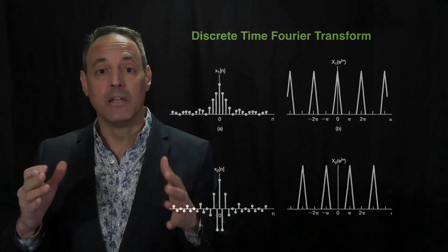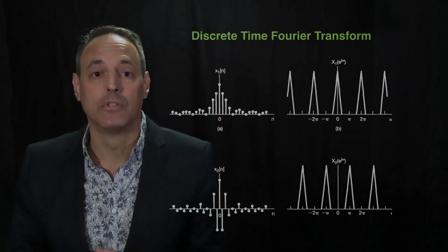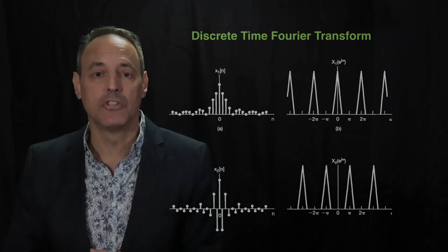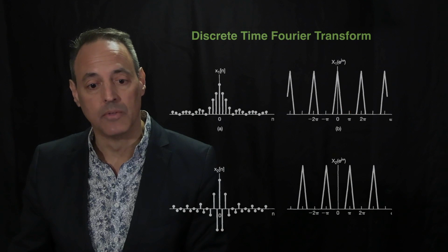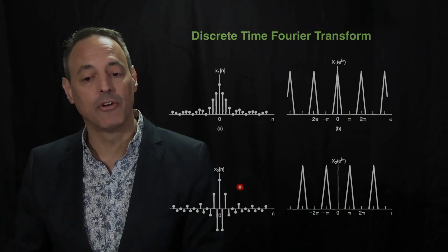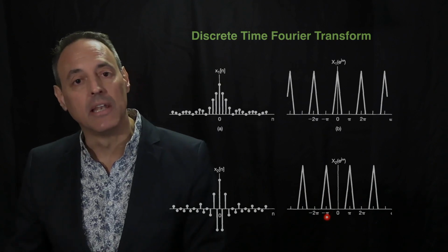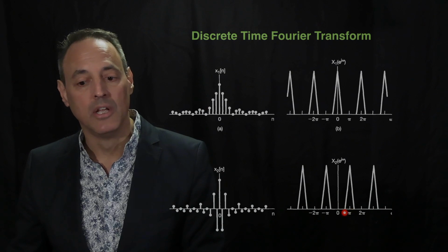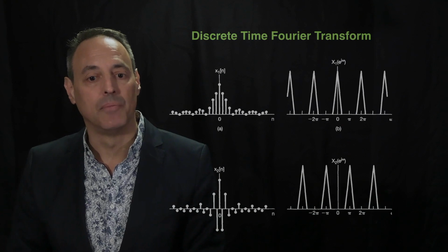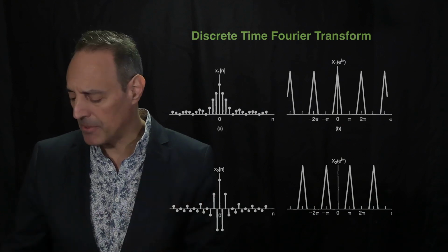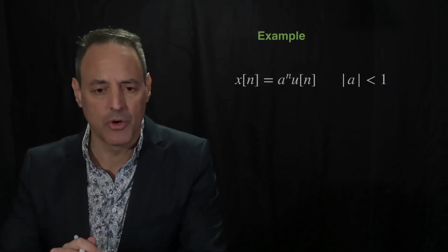So in the Fourier domain, whatever lives on the interval negative pi to pi just repeats itself in both directions, which is different than the continuous time Fourier transform, which doesn't have that repeating pattern. Here's a second signal, slightly different, and this is what you get for its Fourier transform. Notice now you're still repeating on the interval, but negative pi to pi looks quite different. Everything gets shifted over by pi in this signal. These are just representations of the discrete time Fourier transform, and it'd be helpful to do an example to show how this works out in practice.